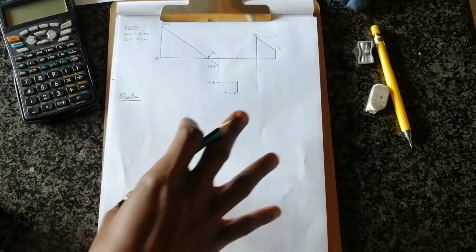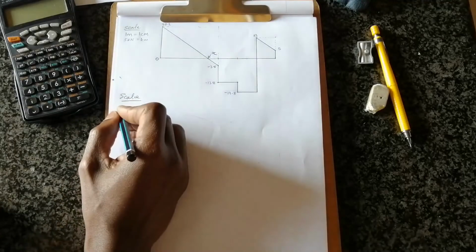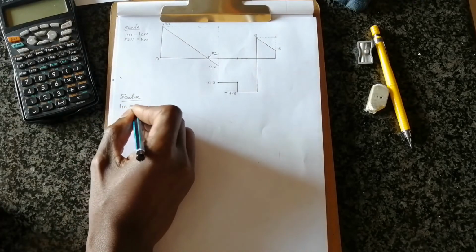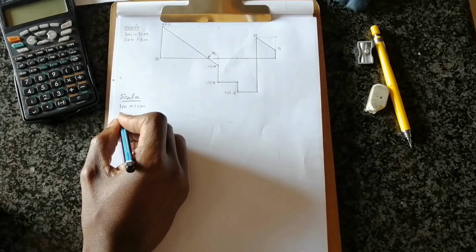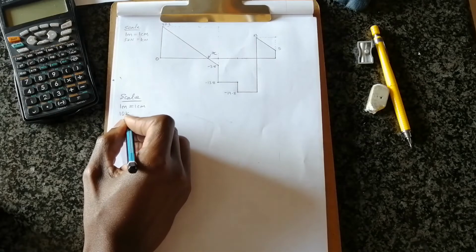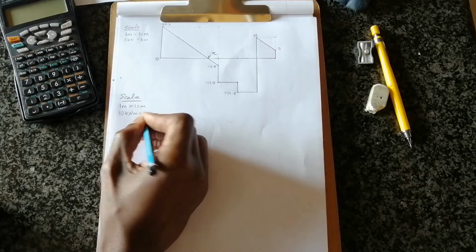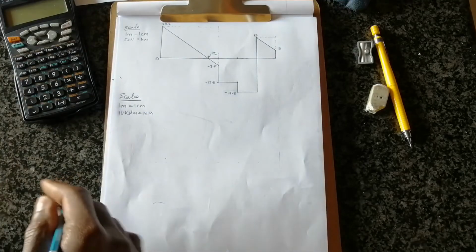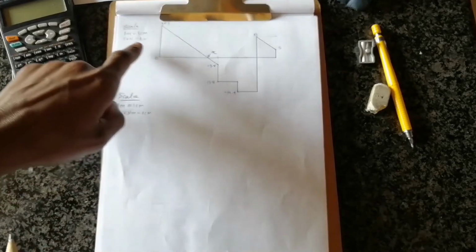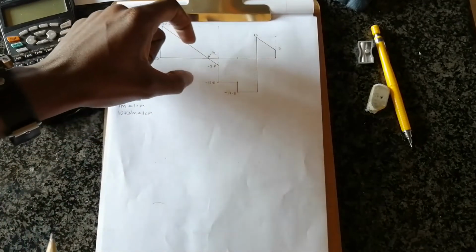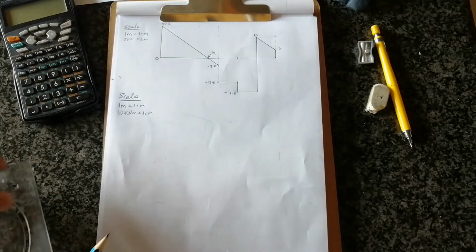We state our scale for the bending moment diagram. We'll say 1 meter is equal to 1 centimeter. You can state it there, and then for our kilonewton meters, we'll say 10 kilonewton meter is equal to 1 centimeter. Now this is up to you and how you want your diagram to be. The scale determines the size, it does not change the shape. If you use a different scale, it just alters the size of your diagram. I think this will be a good number for us.